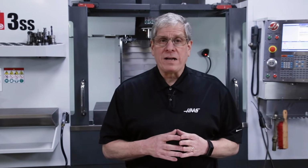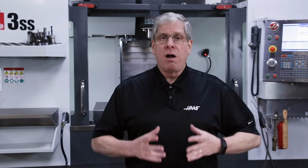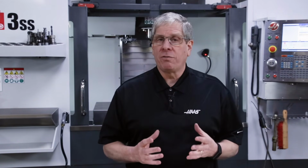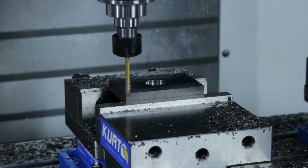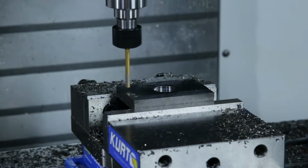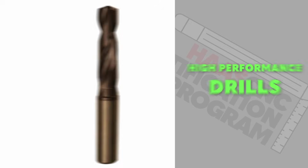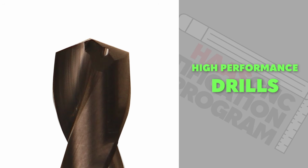Cutting tool manufacturers also offer different coatings to enhance longevity on harder alloy steel and tougher stainless steels. Most drill geometries will work acceptably on all materials, aluminum and the steels. Sure, there are high-performance drills specifically designed for each of these materials, but they're best utilized in high-production, high-volume applications.